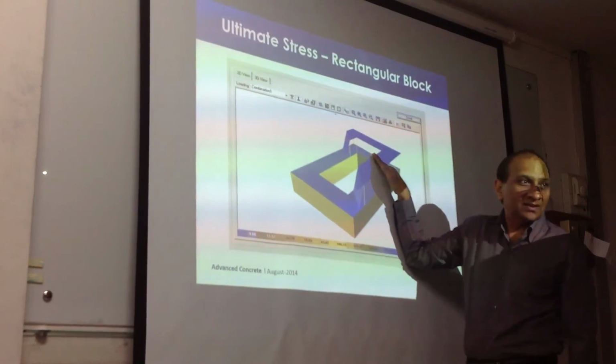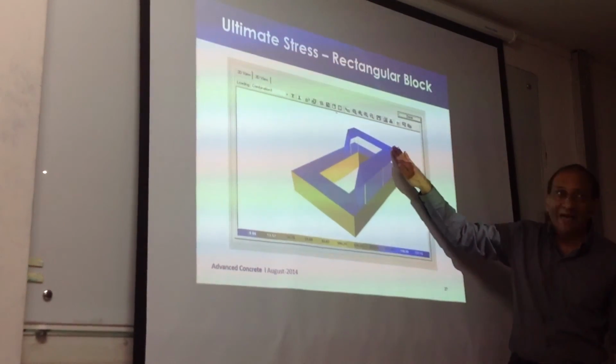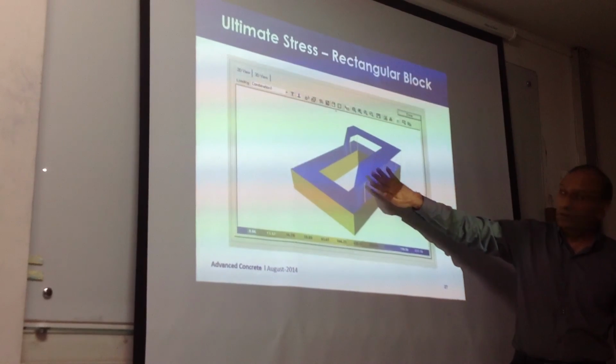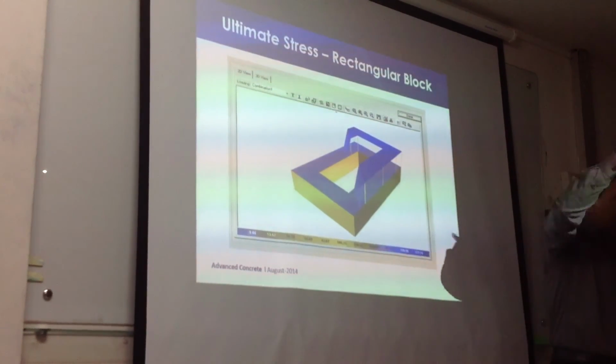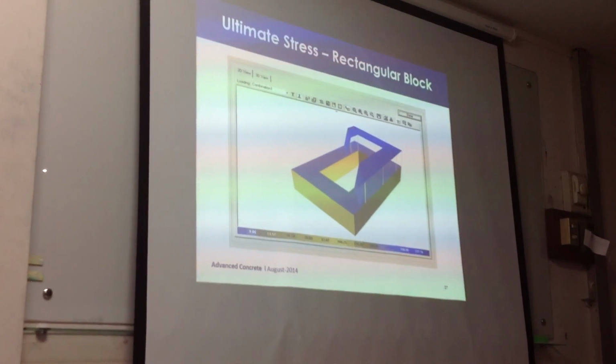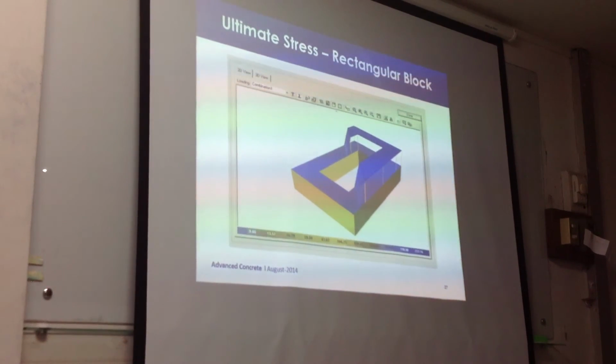This is not flat. We have seen, depending upon the type of the curve, the shape of this thing will match with the stress-strain curve. This is actually the stress-strain curve, correct? So that means if there's a curve here, we have a surface of stress over the cross section, and to calculate the integration of that on a complex cross section is very, very hard, and that is why those equations are not so friendly for hand calculation.